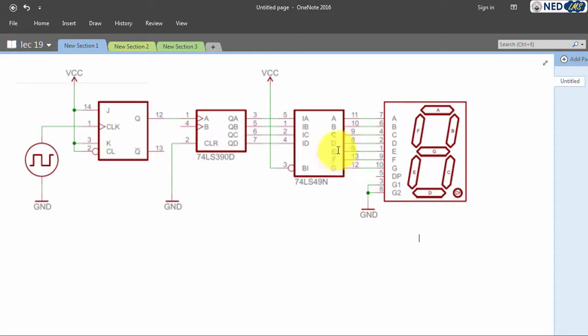So if you see a fan out of 10 in the data sheet, it means that the single output can drive 10 inputs of the same logic family, such as CMOS or TTL, etc. You will learn about these logic families in your digital electronics course. Now suppose that I'm discussing this 74 low power Schottky transistor. Let's ignore what the numbers are.